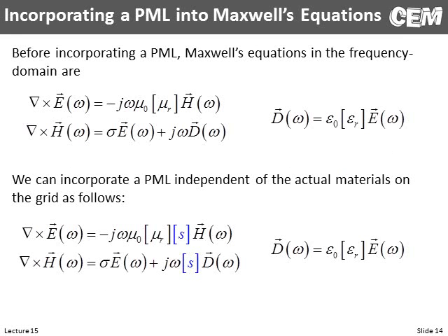Now the perfectly matched layer really fundamentally is a frequency domain concept. So in fact, it's incorporated into Maxwell's equations in the frequency domain. Since we're formulating a time domain code, we then need to jump to the time domain, but now with the PML terms in here, and that's where things get ugly, because we have complex numbers that become integrations, and things get a little bit more involved.